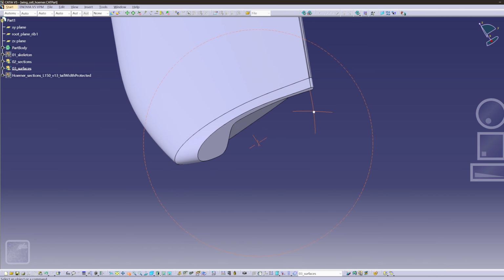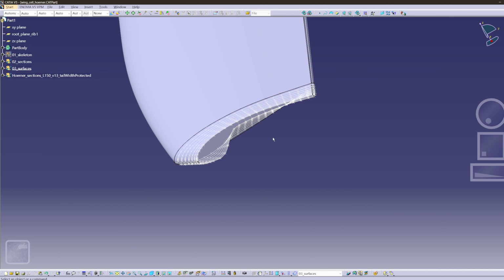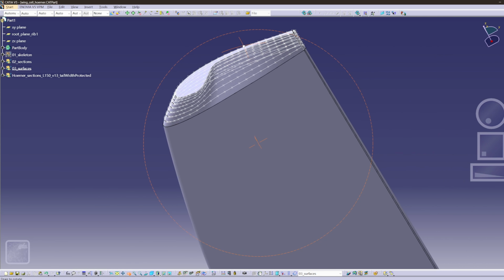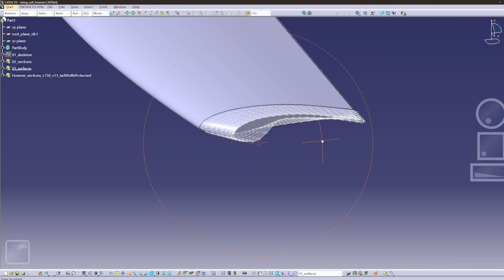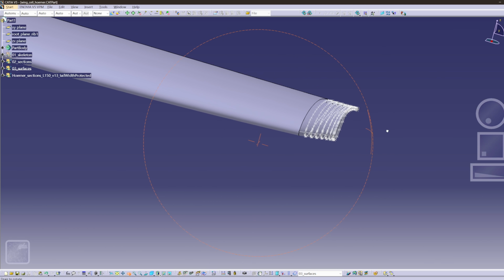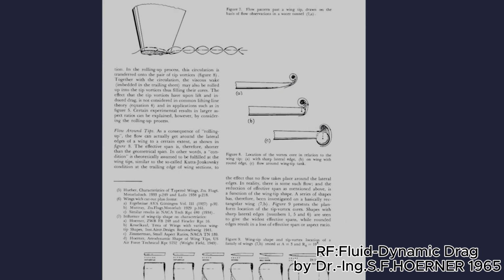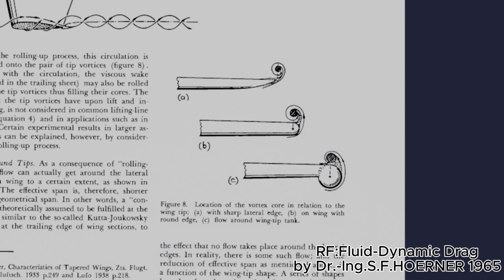Next is the Hoerner wingtip. This classic configuration uses a contraction design on the lower side of the wingtip to effectively alter pressure distribution. It blocks the high-pressure airflow from rolling over the wingtip to the suction side, creating a counter-rotating micro-vortex at the wingtip edge, which offsets the intensity of the main vortex. For small aircraft, the Hoerner-type not only provides significant drag reduction during low-speed cruise, but its unique geometry also grants the aircraft better stall characteristics, making flight more stable.